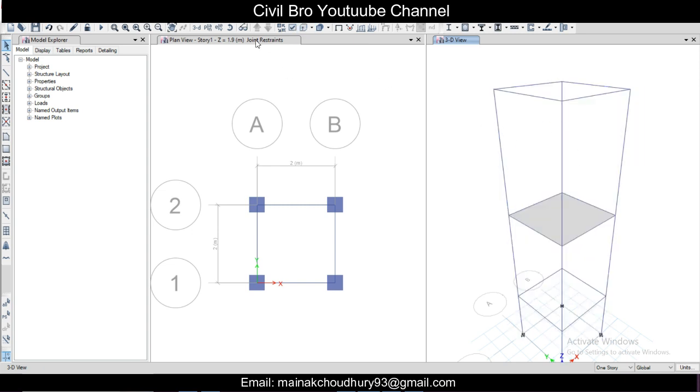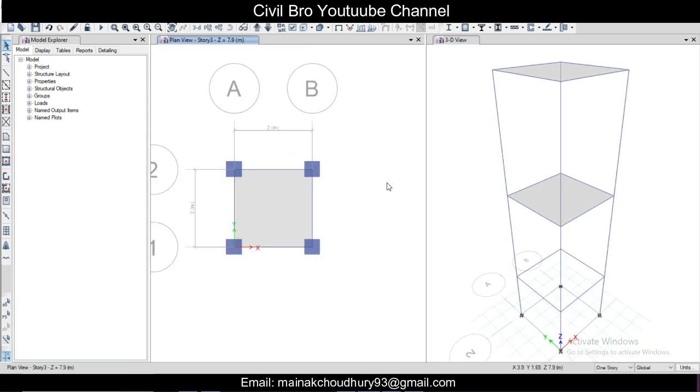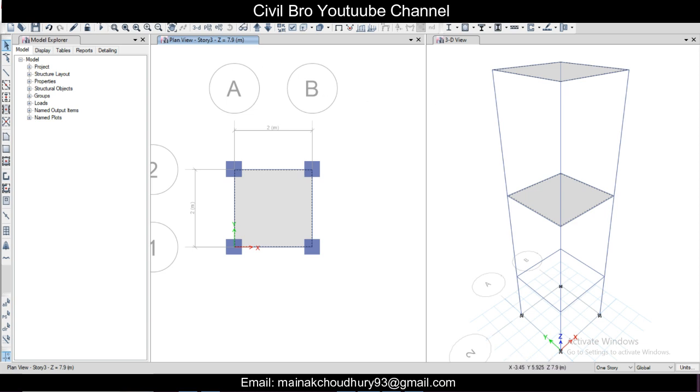So I think the topmost floor didn't copy the slab, so we'll just assign the slab here, no problem, slab 150, click on this, we will assign. So this has been assigned, supports have been done. So let's put the loads, select the slabs. You can also use the select option for that. Select by object, select and select the slabs. So there are only two slabs selected like this, and now we'll go to